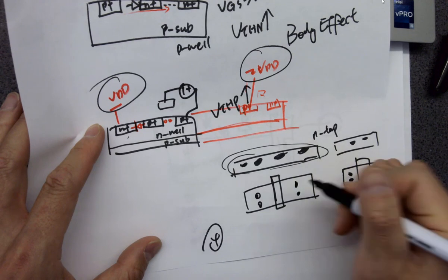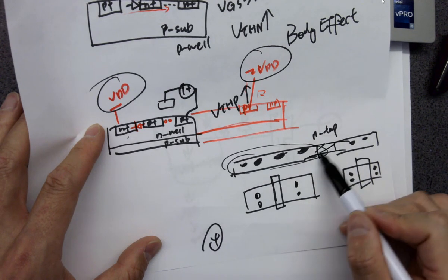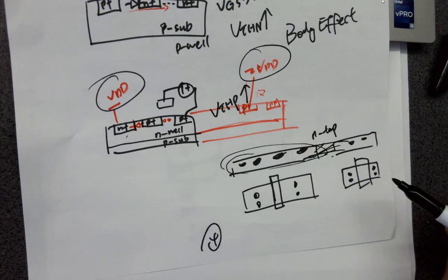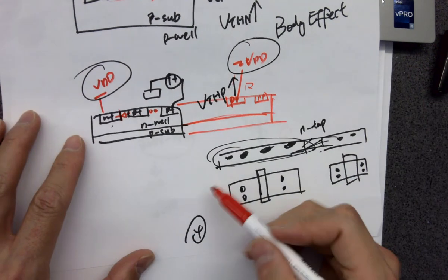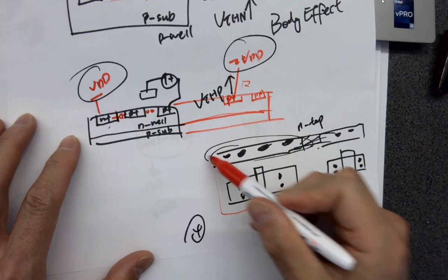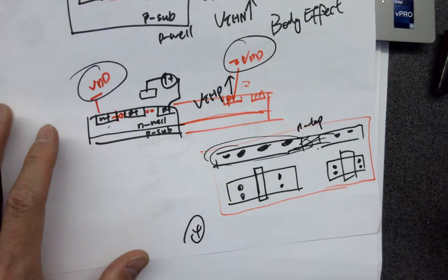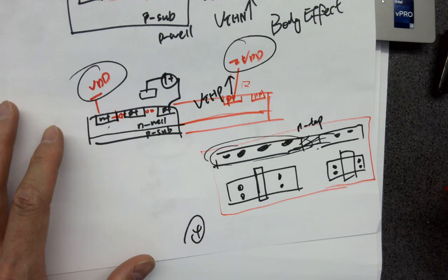Even though we didn't do that, actually all these are interconnected. So basically they share, even though they don't share the same N-well, we should have done that, but I don't think we did that in our ALU layout. So after you finish all the layouts, you should actually draw a pure N-well layer to cover all the PMOSes.